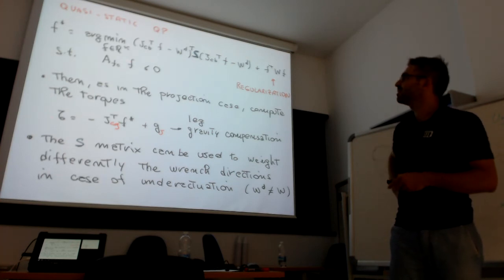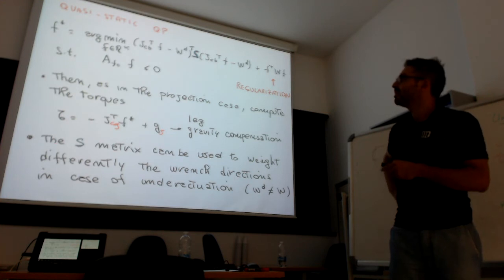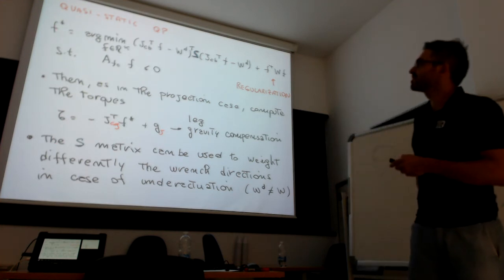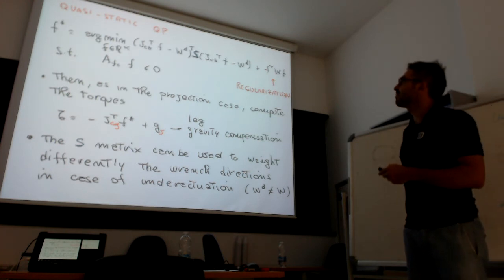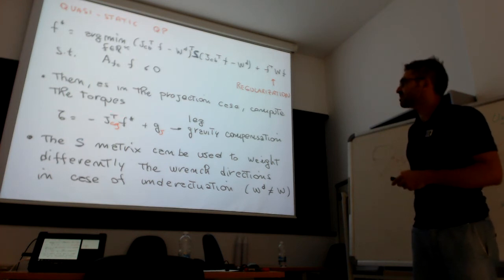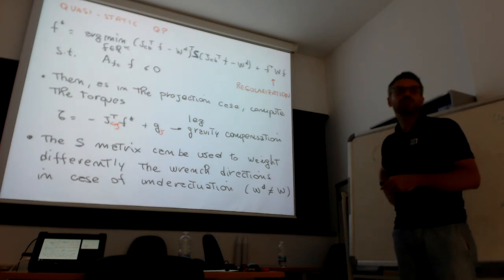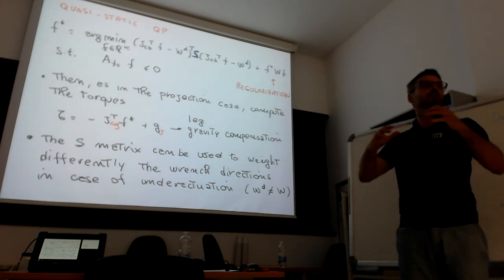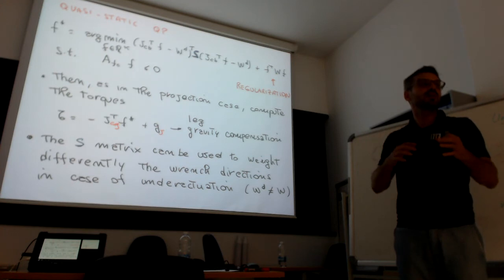I would say it's both of them. They are just the first stage that does the mapping from range to contact forces, and the last stage that does the mapping to the torques. Okay. So it's a kind of, remember the coupling of the floating base and the actuated part.